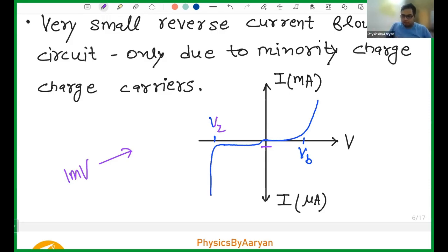So you can clearly see we can give as much current to the Zener diode, and you can see your voltage is not changing. Current is changing, the y-axis is changing, but you can clearly see that your voltage is not changing. So that is what our stabilizer does. Even if a large current comes from behind, your voltage is not going to change. That is the whole purpose.